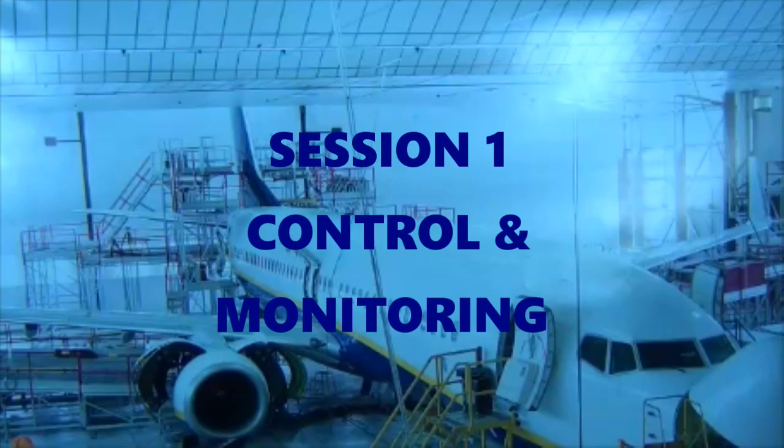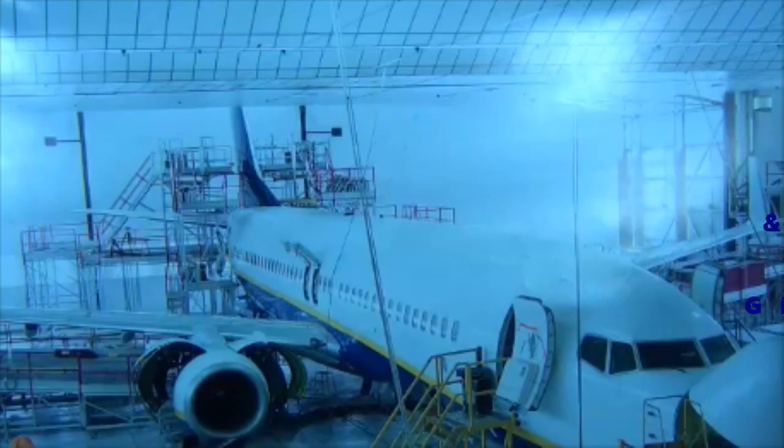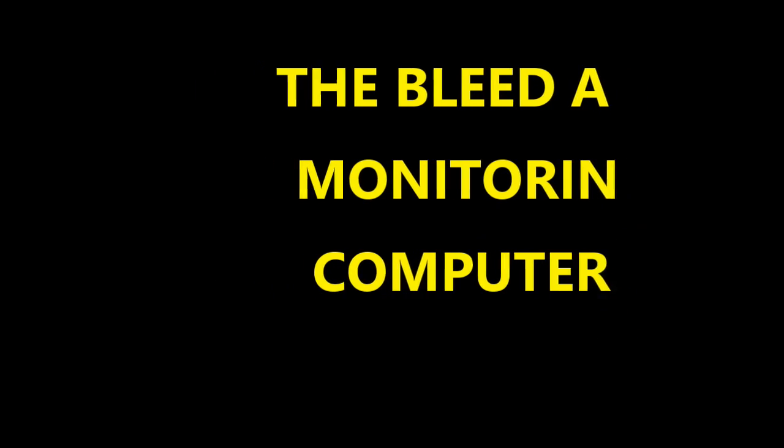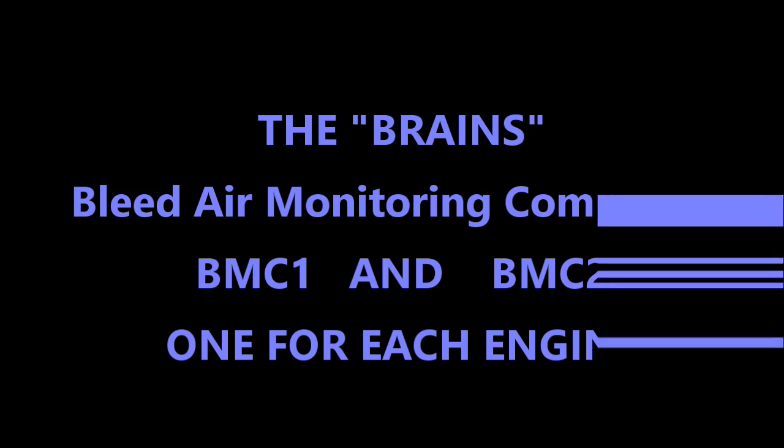As I mentioned before in the other topics, you have, of course, computers that are very heavily running things automatically. So we have the same thing here in the pneumatic system. There are two computers. These are the bleed air monitoring computers, and they are named BMC1 and BMC2, one for each engine.